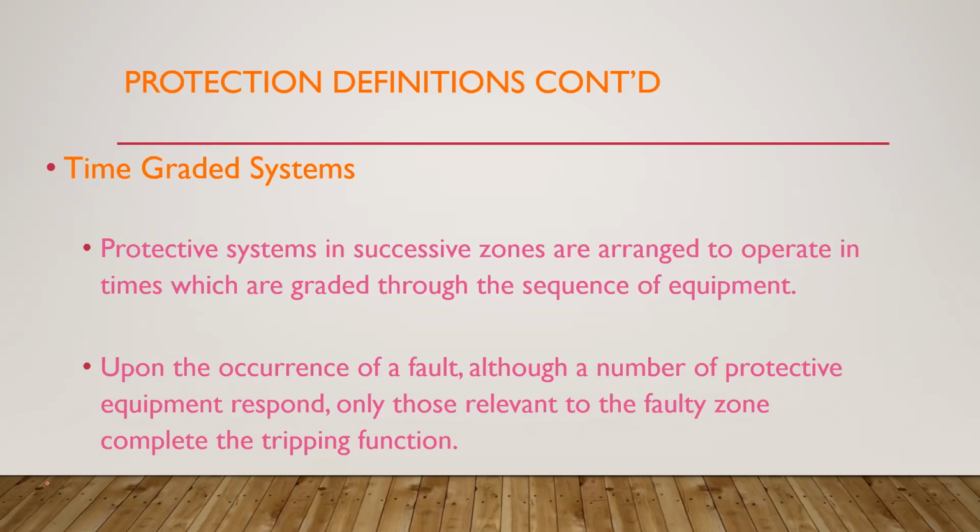It should have been physically inspected by the supervisor, but he didn't. A man just said, yeah, I did it. He said, all right, you can re-energize the line. They re-energized. And so when they re-energized, what they did was to energize a three-phase to ground fault. That's what they created. A solid three-phase fault.